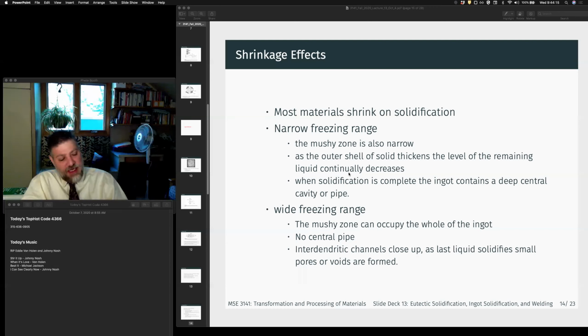Anytime you have liquid processing of metallic materials, right? Whether it's a casting or a weld solidification, you're going to have defects, right? There's no way around it, right? A huge part of designing a weld joint and designing weld filler metals and weld processes is managing those defects, right? Is getting your process window in a range where they can be minimized. But anytime you have liquid metal processing, you have defects.